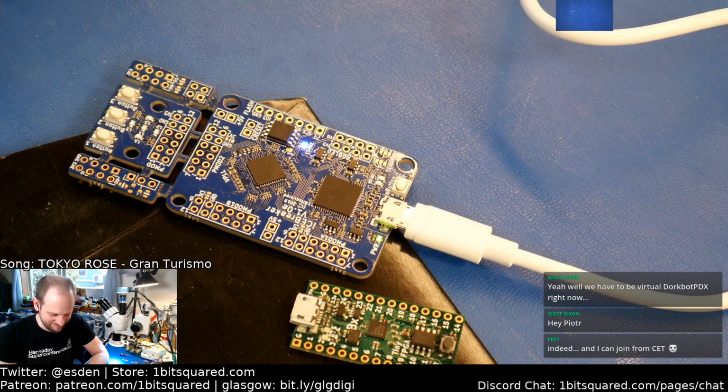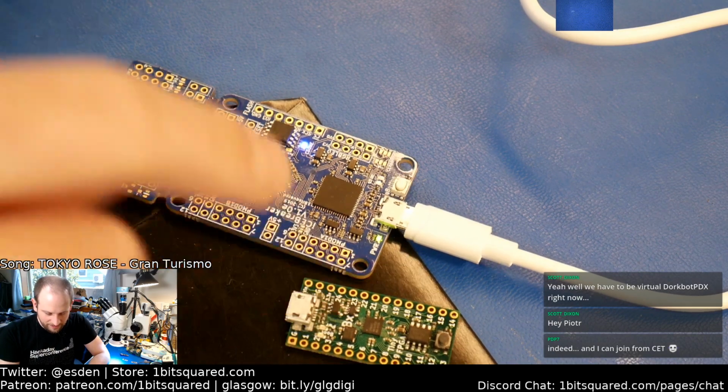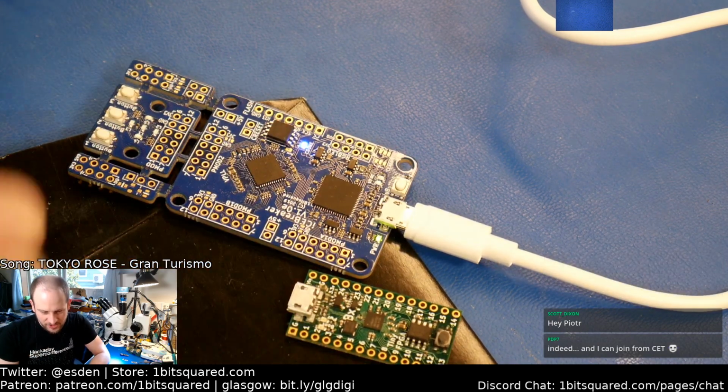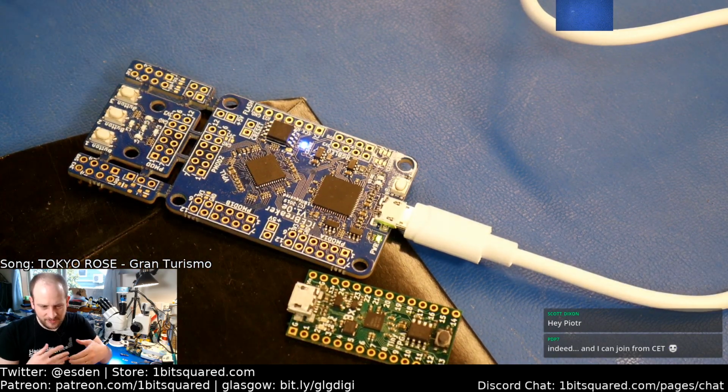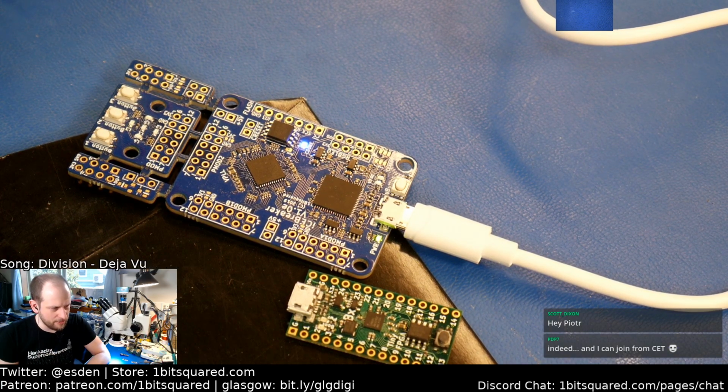Okay, so going back to the Tiny FPGA. So Tiny FPGA essentially has two bit streams, the bootloader bit stream, and it can use the special block inside the FPGA, which is called a warm boot, to reset itself and load a different bit stream from a different position in the flash. I think there are several slots for it, but in this case we are using just 2 slots.